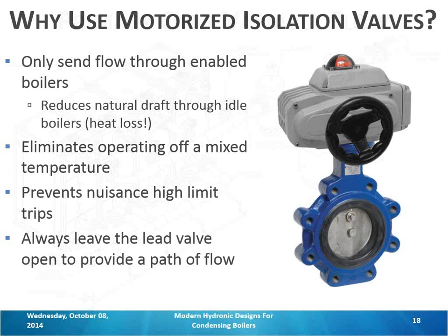So the BMS controls those valves? Could. It depends on whose package is being provided and what's written into the specification. Typically, a boiler controller will control the valves because then nothing gets out of sync. Because the boiler knows when the burner has a demand. But you'll see some where the BMS is controlling it. Same as a boiler pump. Sometimes the boiler controls it. Sometimes the BMS controls it.